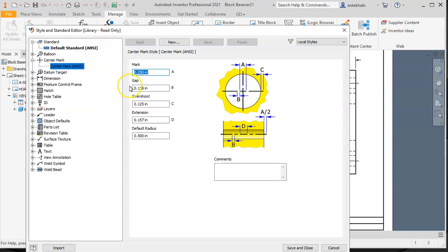Under the style editor, you can change the center line here, or you can also change with a right click on the dimension itself. Right now, since we're in the settings, we can change all this to divided by 2 for A, for B, also divided by 2. Oops, I did not delete that IN. You should delete that inch mark letters.